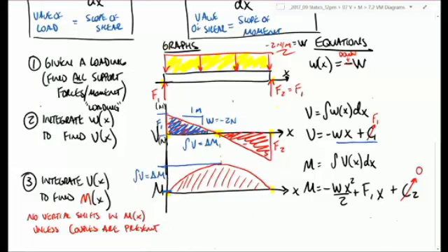Okay? So not only can I draw the functions, but I can actually find the value of that maximum moment simply by finding the area of a triangle. Right? And triangles are easy, 1/2 base times height. And so all you need to know is the F1 times half of the length of the beam divided by 2, and you'd have the value of the maximum moment. Okay? Or you could work through these equations here.